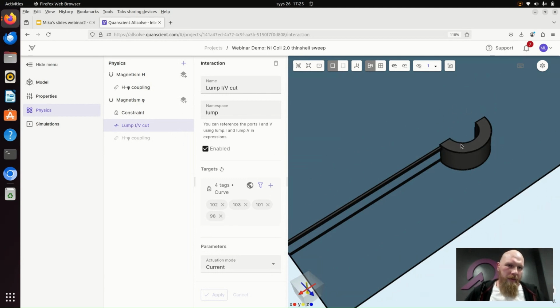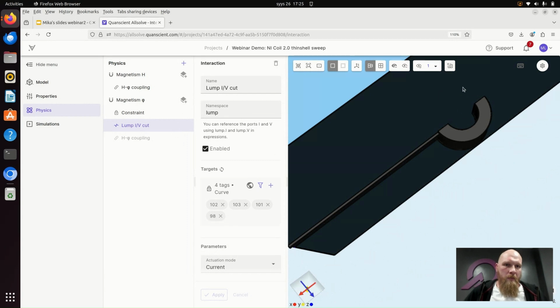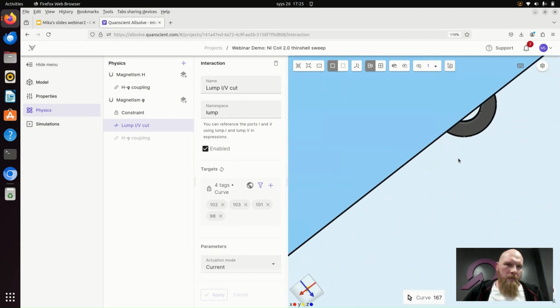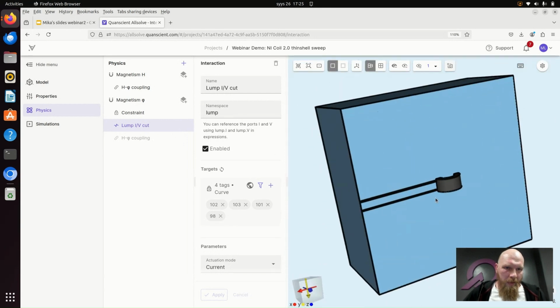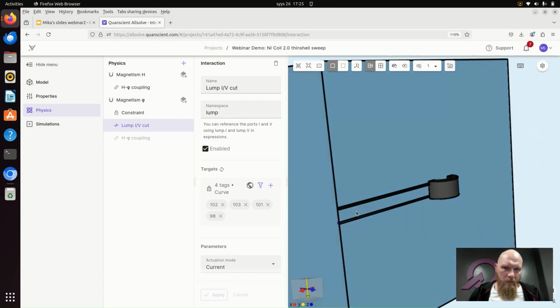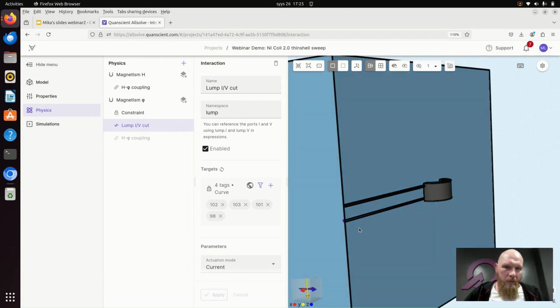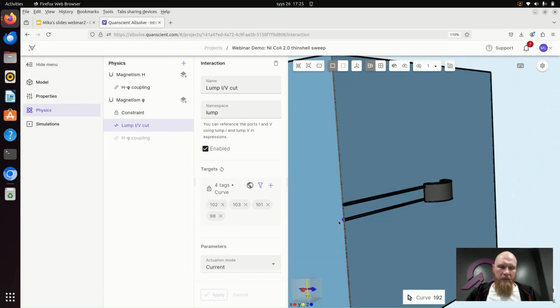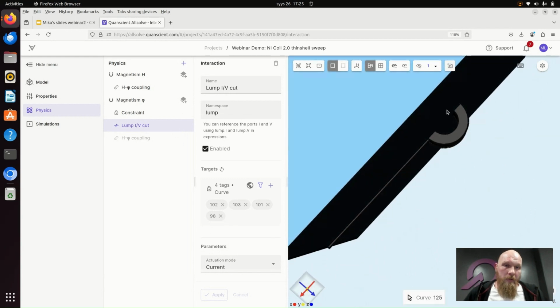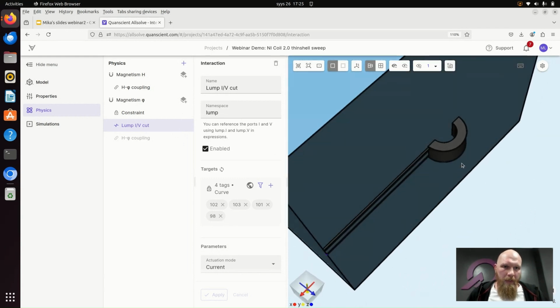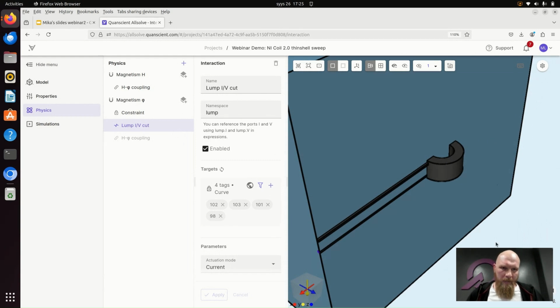And for the non-insulated winding, we don't even know what the current is. But in Allsolve, this is done automatically behind the scenes. So the user only needs to define the currents which are known. So you only want to address the current to the cable, and we automatically solve for the currents behind the scenes for the unconstrained.